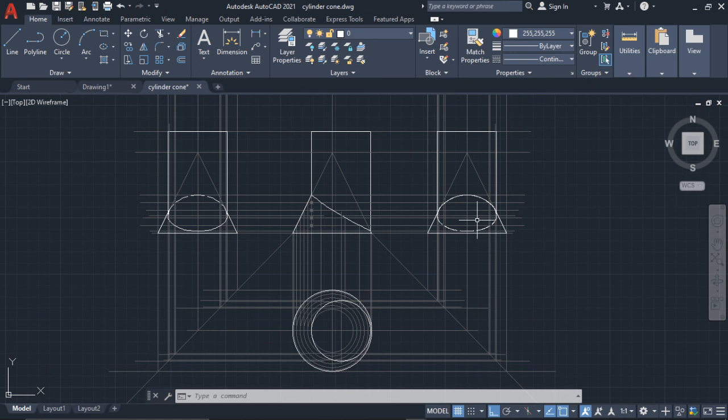So this is in broken lines because this is the left side view. So in first angle, the left side, which is what you'll see here, would be projected over here, and then the right side, which is what you would see over here, would be projected over here. Good. So that is how you go about completing the drawing. And the reason why this is in broken lines is because if I'm looking from the left side, then this would be in broken lines below here because I'm not seeing it. The curve at the top would be in solid lines, and vice versa. So over here, this is in solid lines, because if I'm looking from here, I would see this part in solid lines, but the back would be in broken lines.